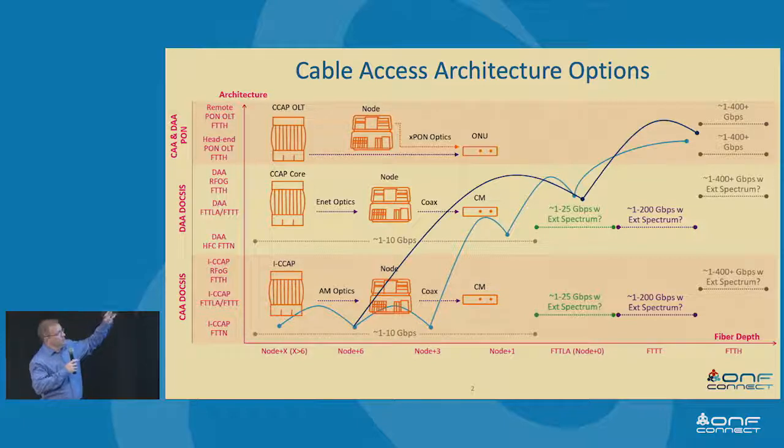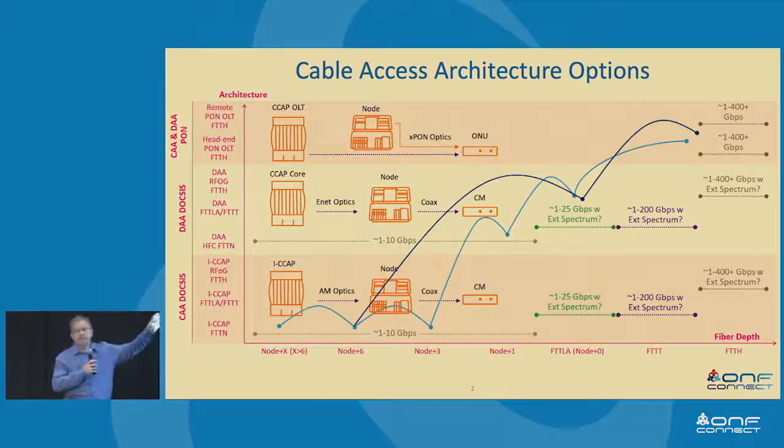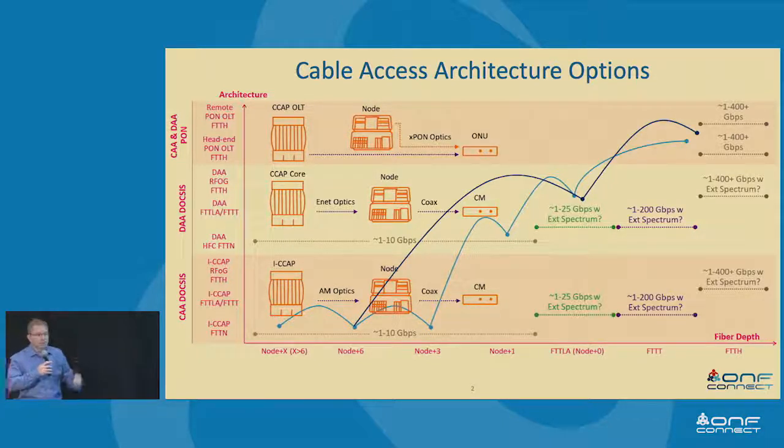Now, the operators are on a really neat journey. So Cable Labs, the organization behind a lot of the standards that help drive many of these systems, said, well, we could distribute a lot of the actors that are inside this chassis, this CCAP core chassis. We could move some of their functions out into these node devices. So the first one that was up was moving the PHY modulation. So today, these boxes will have F connectors on the back, right, that present themselves into that optical transmission. Well, those F connectors come out, and then they show up down in the node, 10, 20, 30 kilometers away.